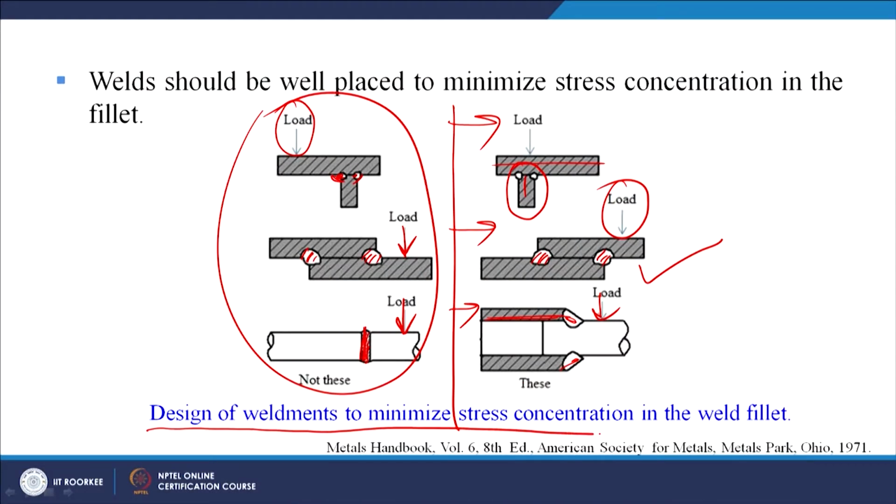So the weld should be well placed to minimize the stress concentration in the weldment. So this is the design of weldments to minimize stress concentration in the weld fillet. This is something which is better. These three design configurations are better as compared to these three.